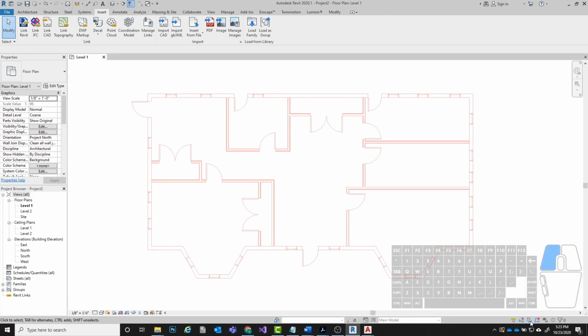If you toggle this, you'll see now I have a little red X next to that pin there, so I can turn that on and off. You'll know that it's turned on when you get the red X. But now, if I try to highlight this and I go over top of it, I can't touch it anymore. I can't click on it. I can't move it around. That's what you want, because again, we're going to be tracing this, and we don't want it to constantly be popping up and interfering with what we're doing.